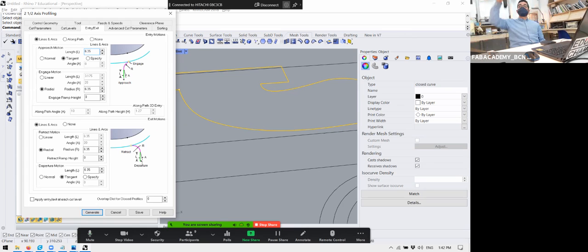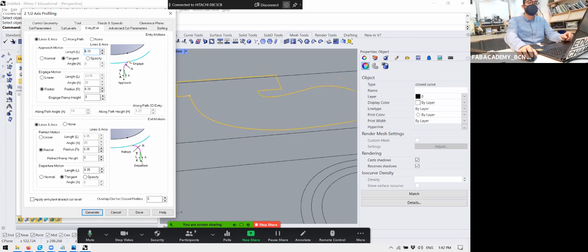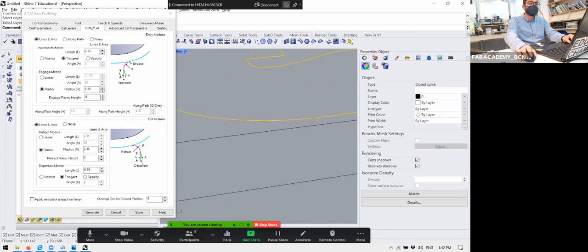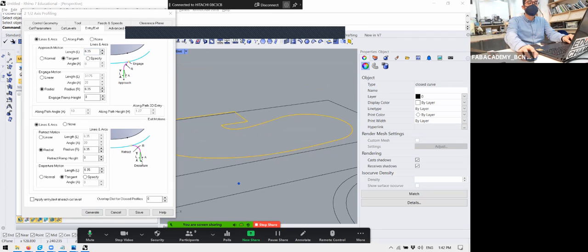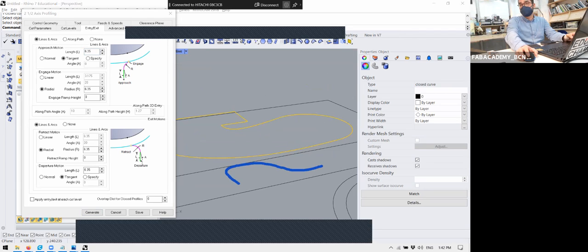We are cutting with a down cutter, no? We cannot do this movement. We need to enter with a slide. By default, it does not do the slide in the line. I will draw it, for example, but it will enter outside of the material, turn, and do a slide to enter cutting. This is good.